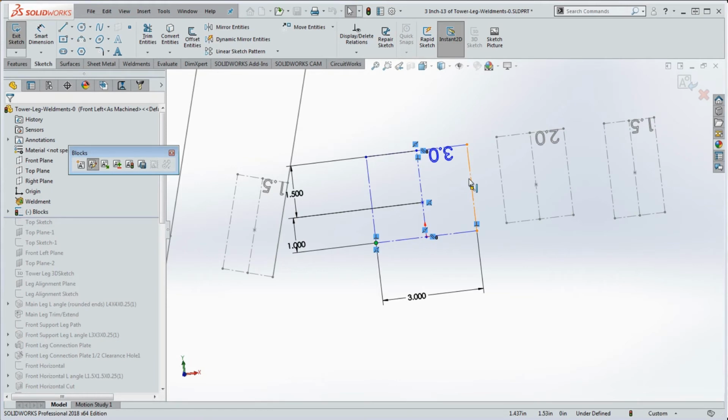It's going to be right where the two wings of that structural member come together, the backbone of it, you might say. You have one wing coming out this way, and then you have the other wing going perpendicular to the screen, away from the view here. So that's going to be the backbone of our structural member. This is going to define the very front of that because the structural member pass segment is going to end right at that point. So it's going to define the front. It's going to define the left-hand side of it. And then this line back here, we're going to be using that for alignment.